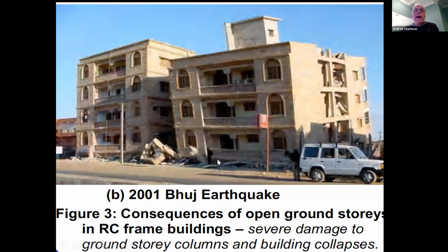The ground floor has collapsed here and here because probably there was car parking under here, and above there's lots of partition walls to make the building very strong. Like, look at this wall here. It isn't even damaged. It's very strong, but underneath it there were just columns.